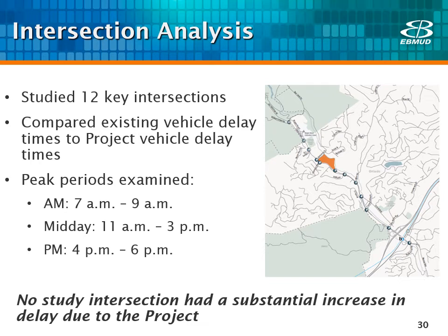Vehicle delays were analyzed for the 60-minute period when the highest traffic volume was recorded at each intersection during all peak periods. In the end, no study intersection had a substantial increase in delay due to the project. This was mostly due to the limitation of truck traffic to outside the morning and afternoon commute periods, and the fact that the project contributions to traffic relative to existing traffic volume on Camino Pablo during peak periods is low.